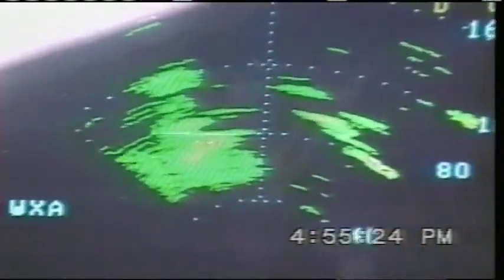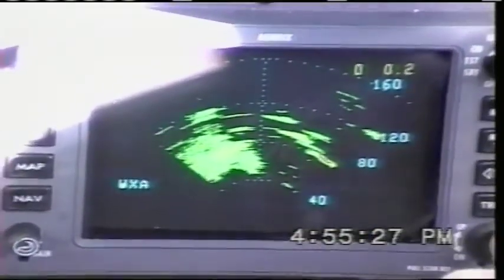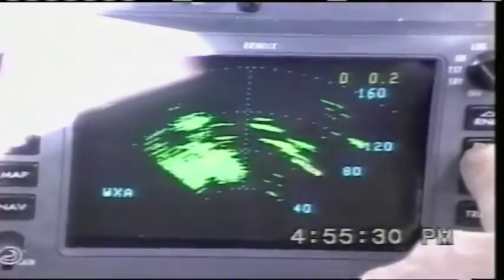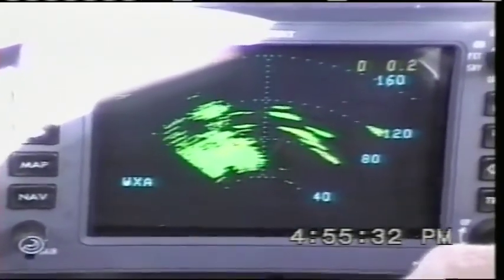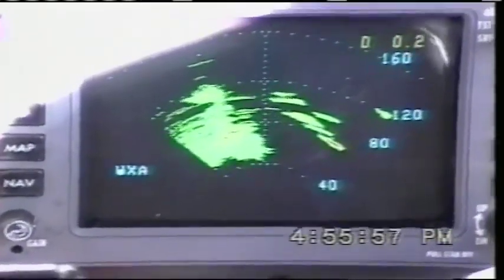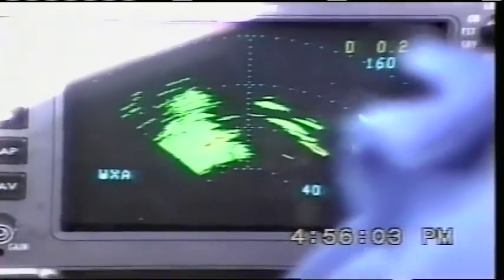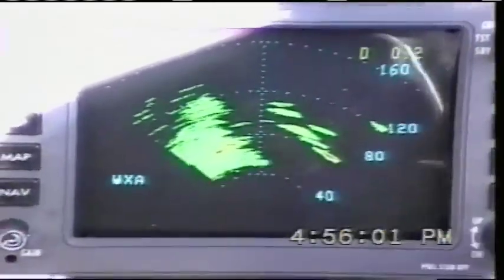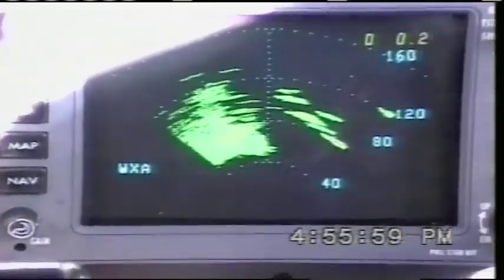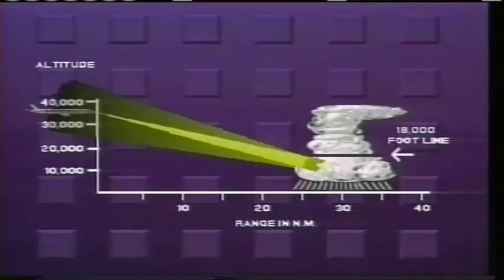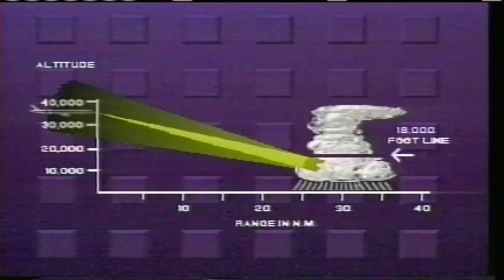If during the flight a radar system is suspected of having poor range performance, a confidence test should be initiated. A radar system that is functioning correctly should display ground returns out to a distance of at least 120 nautical miles. To perform this test, the aircraft needs to be at an altitude of at least 21,000 feet AGL. Rest assured that if the radar will display the ground returns at that distance, it will certainly display the weather correctly. Whenever an en route storm is being evaluated, aggressive use of down tilt is necessary to direct the beam into the lower 18,000 feet of the storm.